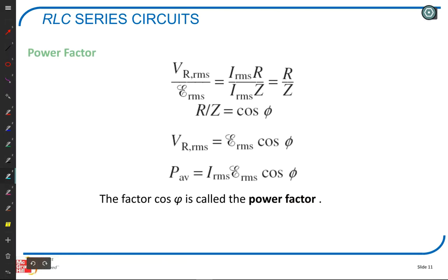There's one more thing. Power factor. Because you have a circuit containing resistor, inductor, and capacitor, the total current may not be in phase with the voltage coming out of the power supply. The power supply can have its peak current at a different time than it has its peak voltage, which seems weird. The power company is charging you for voltage times current.